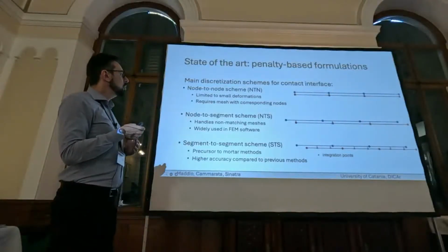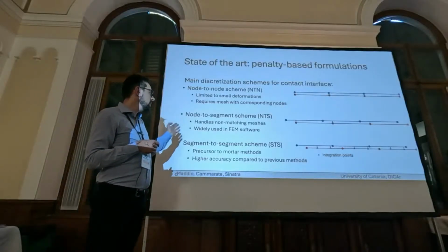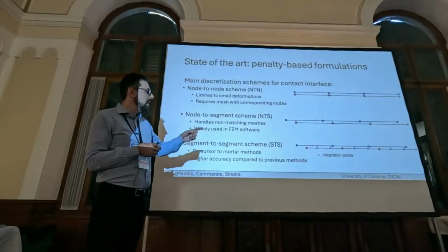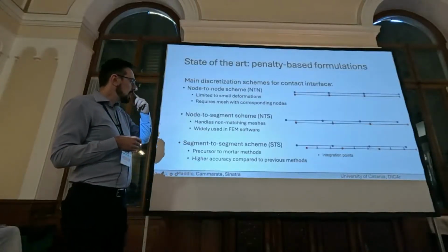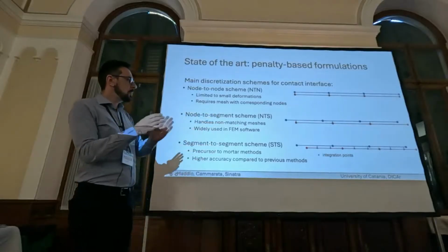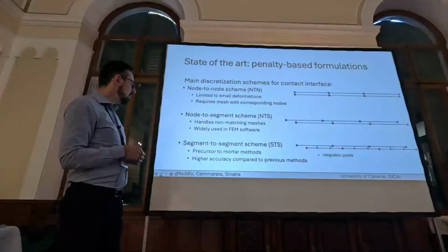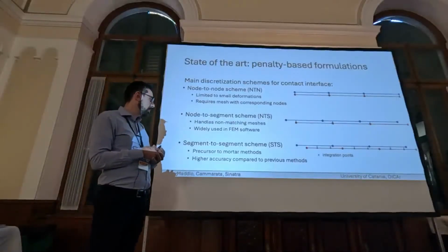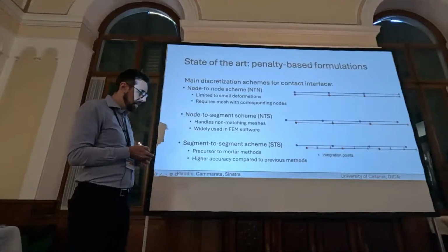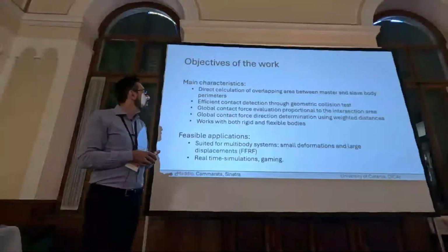Instead, the node-to-segment scheme handles non-matching meshes. It's widely used in FEM software, and it calculates the distance between the node of one body with respect to the segment of the other one. And the segment-to-segment scheme is like a precursor to mortar methods, and it provides high accuracy compared to the previous methods.